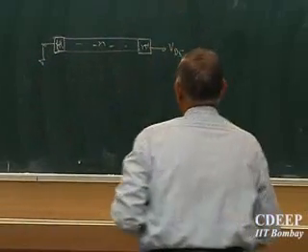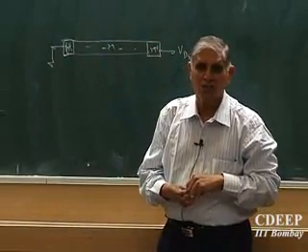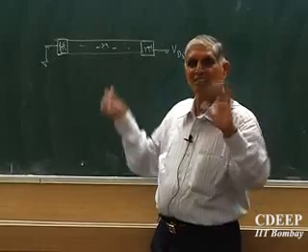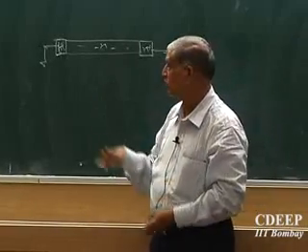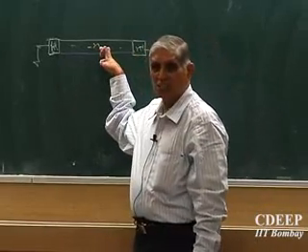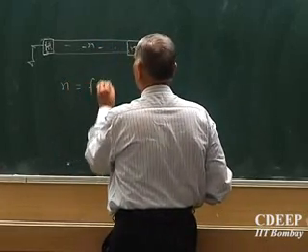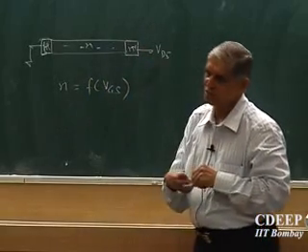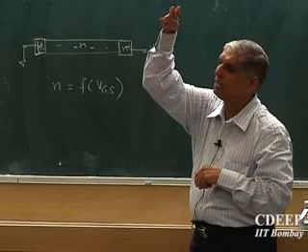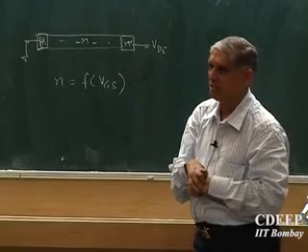Only thing is, we didn't want to call it Ohm's law there. We suddenly say, oh, there are four Maxwell equations, and one of them represents Ampere's law and Ohm's law. The statement is the same, modified to suit what we need. So now we figure out the number of carriers which are going to be created is essentially a function of VGS. How much gate voltage I apply will decide how many carriers, how much inversion layer charge, I can create.